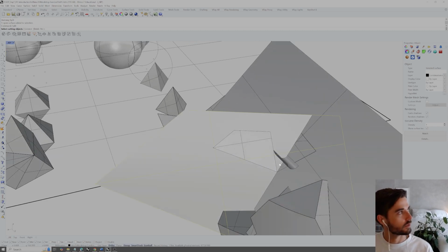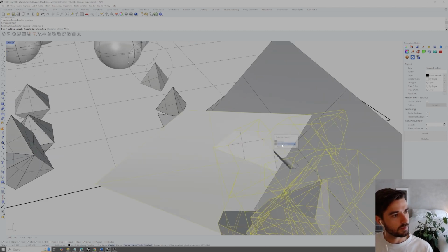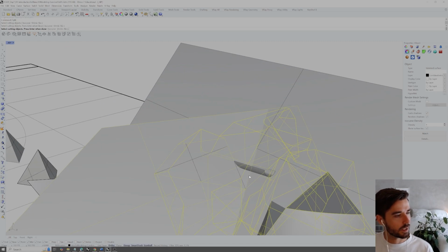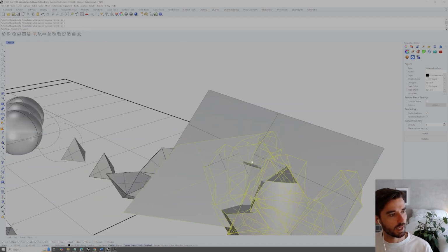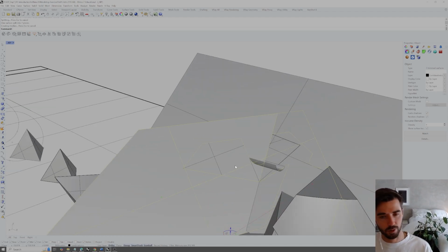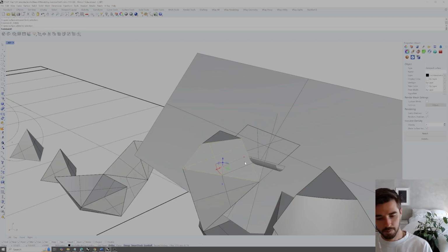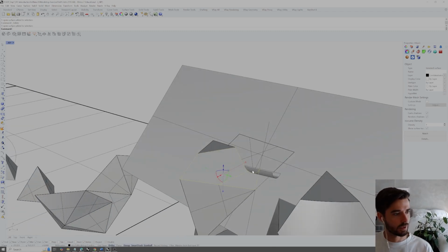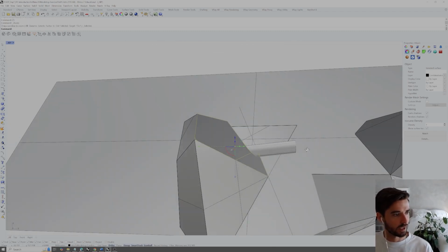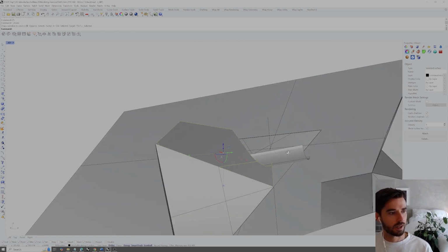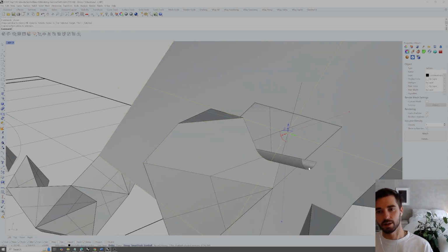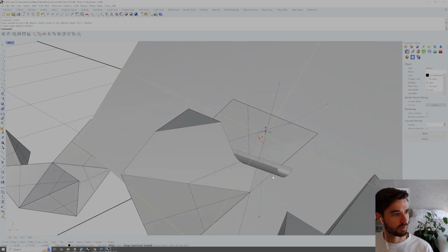And this is why I think it's actually better if we just go ahead and perform the splitting operation here. So use the polysurface, use the line, intersection, and the radius, hit enter, and then what we can do is actually just deselect the part that we want to keep. So control left click, that's the part we want to keep, and now delete everything else that is still in our selection. And then we can delete this original surface, and now we have this new surface that is actually tucked underneath that radius and in the previous plane that we had already had from the polysurface geometry.